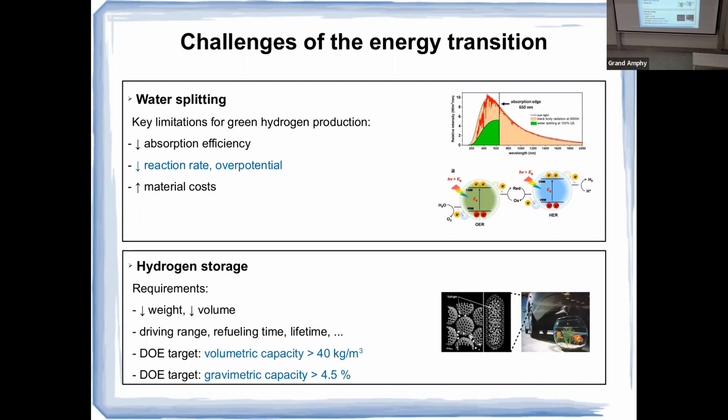Regarding hydrogen storage, let me summarize the problems in this way. We need about 4 kilograms of hydrogen to give cars, for example, an autonomy of 500 kilometers, so they can travel without visiting the gas station. And to store this hydrogen at ambient pressure and temperature, you need a tank that is bigger than the car. So you can think about compressing it.